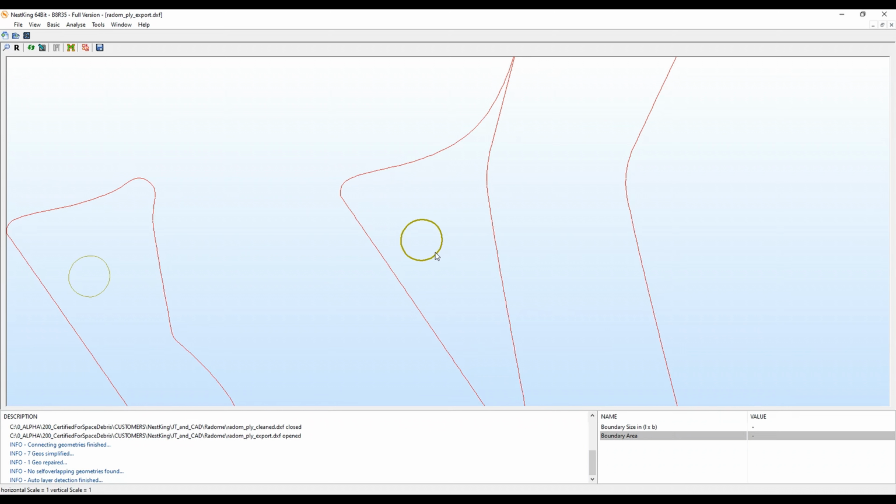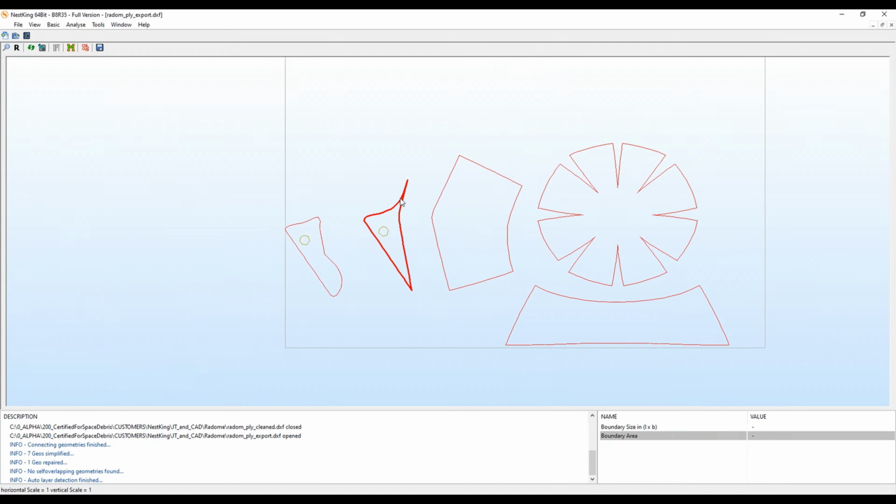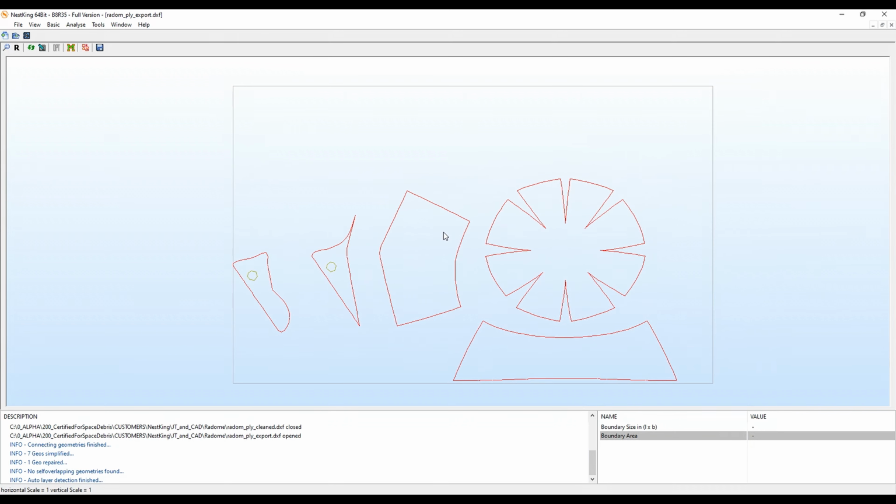The inner geometry is assigned to a different layer, shown by the difference in color, and it connects all the curves to a solid spline and reduces the number of interface points. This is a good feature for later cutting on a CNC machine. It prevents oscillations and even increases the speed of cutting.